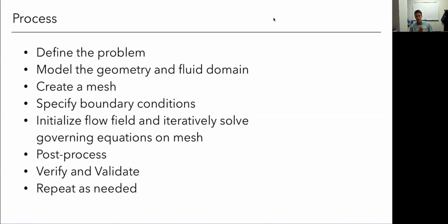This is going to define whether we're using the Euler equations, or the incompressible Navier-Stokes, or the Navier-Stokes, or whether we have to go to an LES, or whether we're going to try and use a transition model. Is there any symmetry, or can we assume symmetry? What type of dimensionality is appropriate? Does this have to be 2D or 3D? Is there a symmetry plane or axisymmetric?